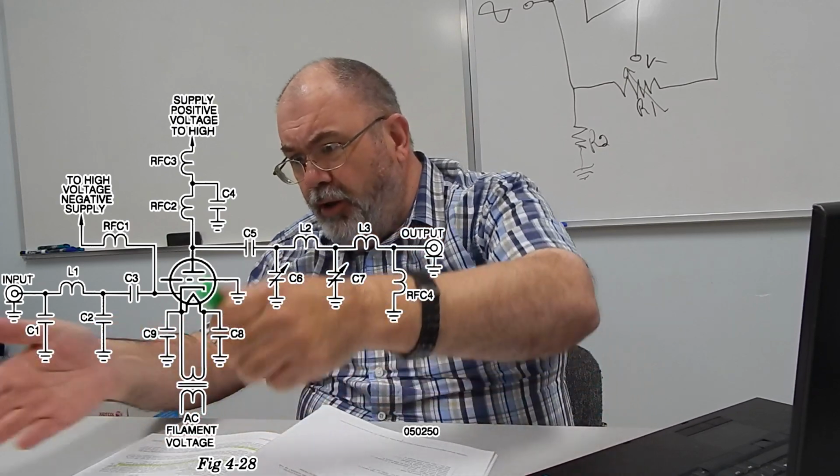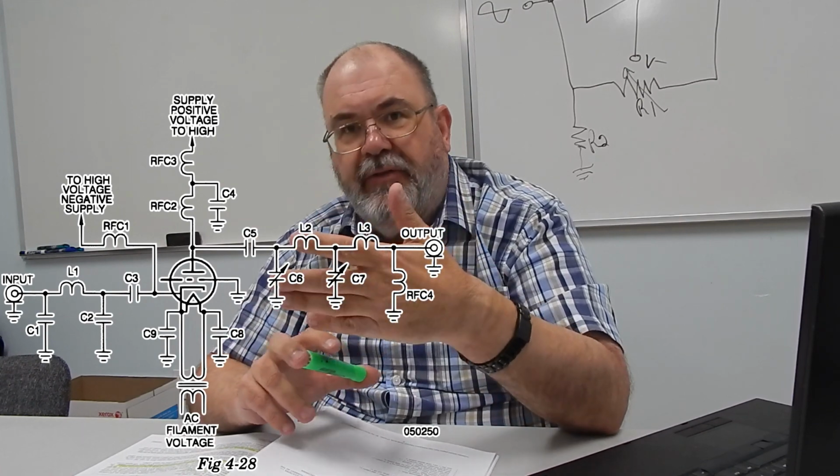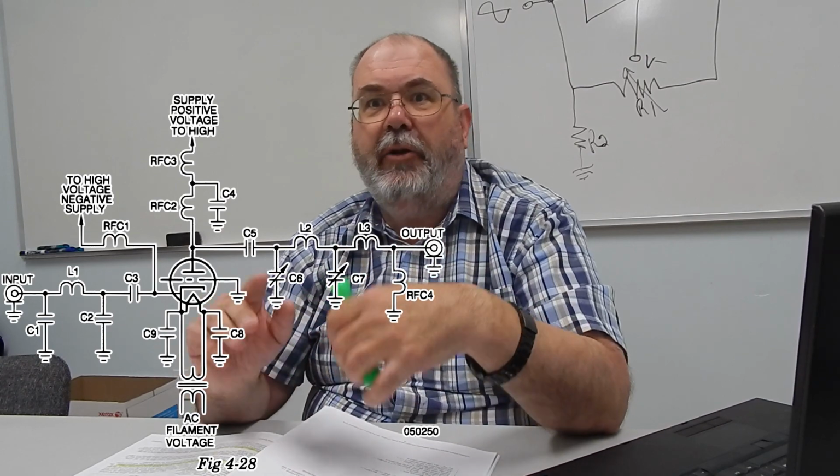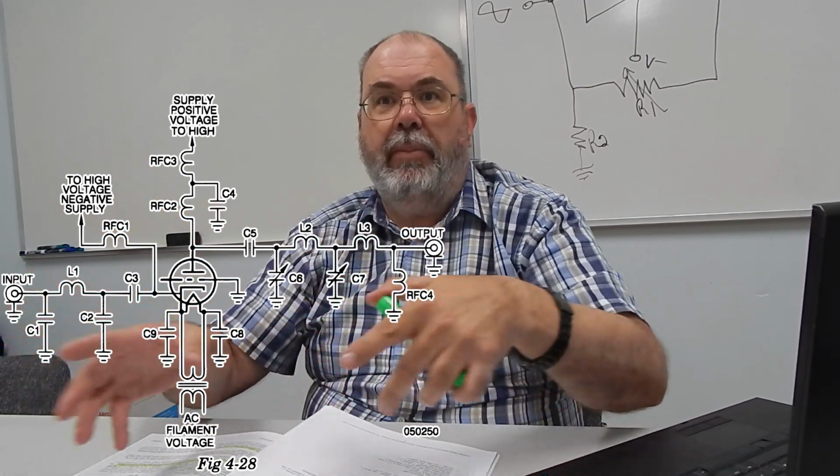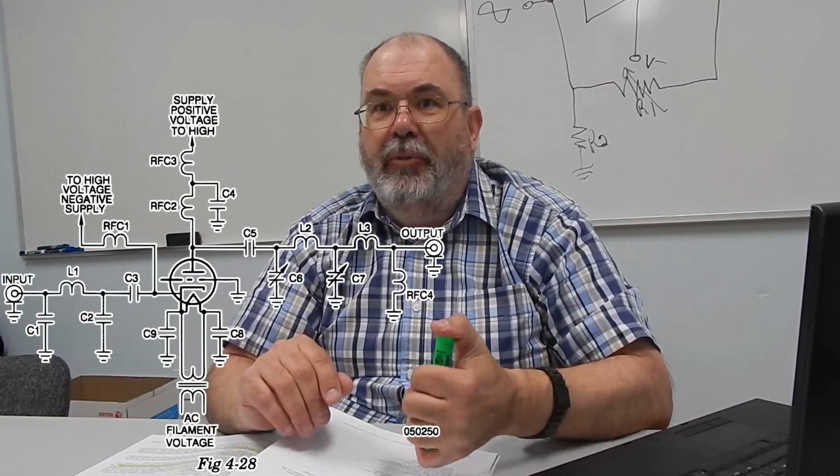And you're looking at it, oh, look at all this power output, but hang on, I'm not putting any power into it. What's happening? What's happening is we've achieved a positive feedback path somewhere in there. And so you have to go through the amplifier and add RF bypass capacitors to ground and series chokes to stop RF from getting into various places. And that whole process of going back and, shall we say, tweaking your design is called neutralization. We need to neutralize the amplifier so any of that positive feedback is gone.